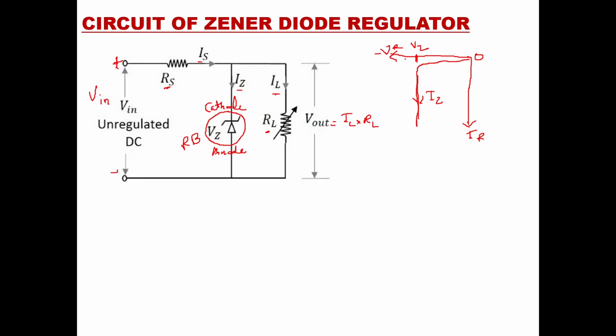Okay, so this is the Zener voltage, and practically the value of the Zener voltage can be around 6 volt or 12 volt. Any Zener you can use, FZ12 or FZ6. Okay, now here is a property of the Zener diode where the current varies but the voltage remains constant. This sharp breakdown is used for regulation of voltage. This is the Zener breakdown, which is used for regulation of voltage.